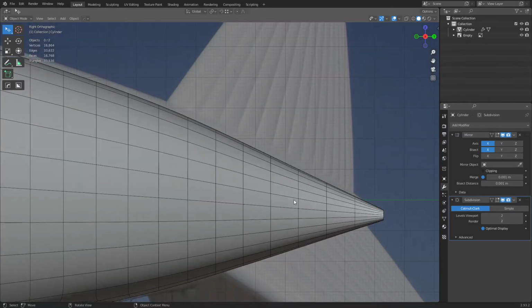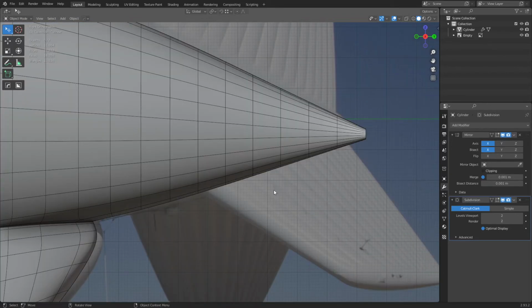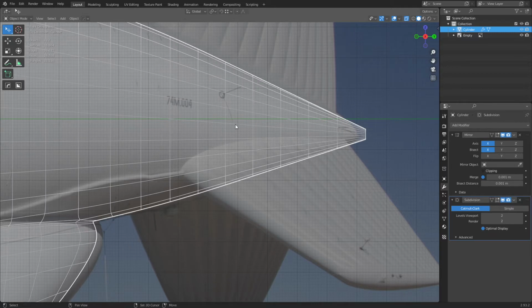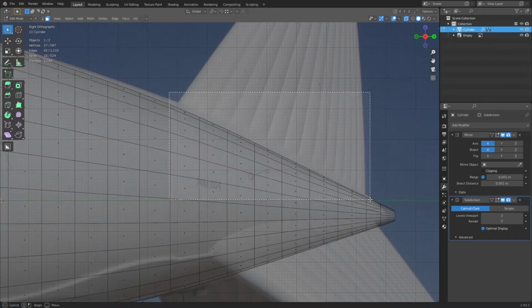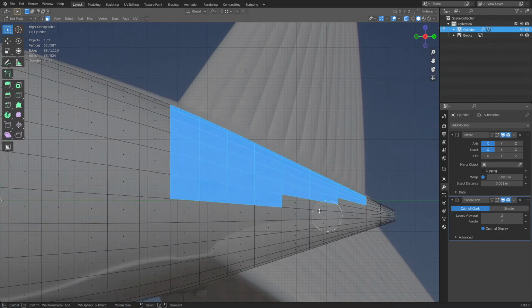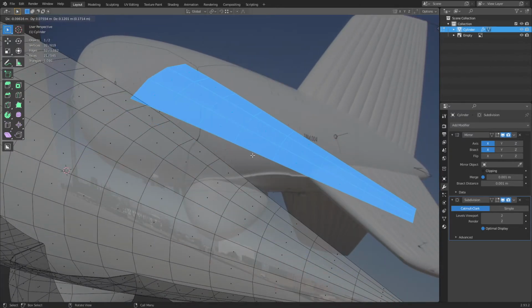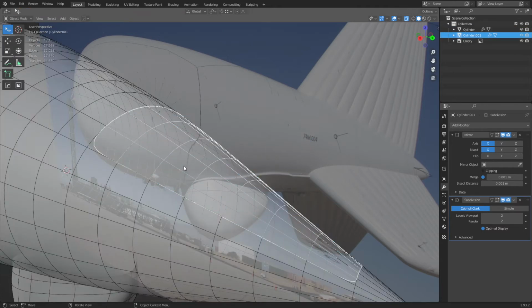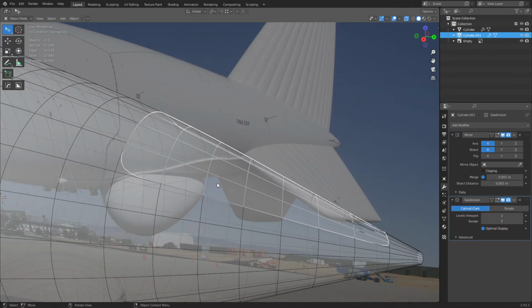This blimp section, or these fins or whatever, obviously there's 3. But I'm gonna start them from their original mesh. So this section, C to use the cursor selector, middle mouse to deselect. I shouldn't need more than that. So I'm gonna duplicate by hitting Shift D, right click, P, separate selection. So we still already have the mirror and everything going on with it. But now we can just work on this one piece.